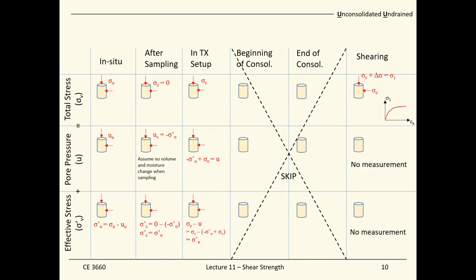Also, since this is a UU test, we don't measure the pore pressure, and this test is only able to give us total stress measurements. So there are no effective stress measurements. One more time, if you need more help on this topic, particularly on this slide, please come to my office hour.